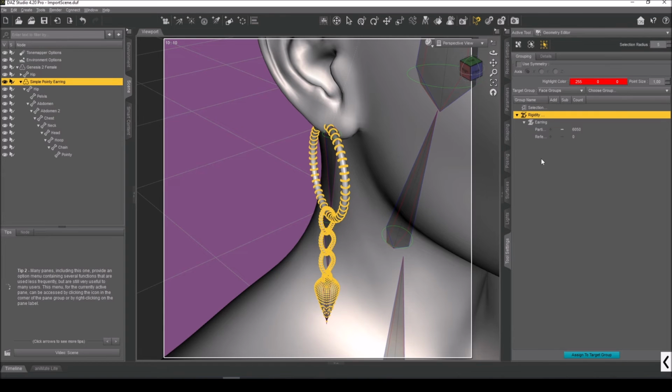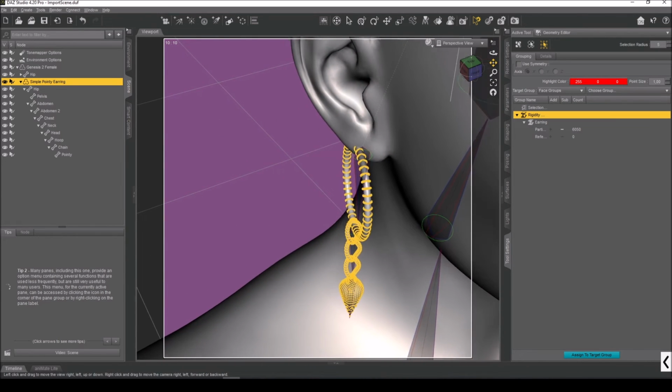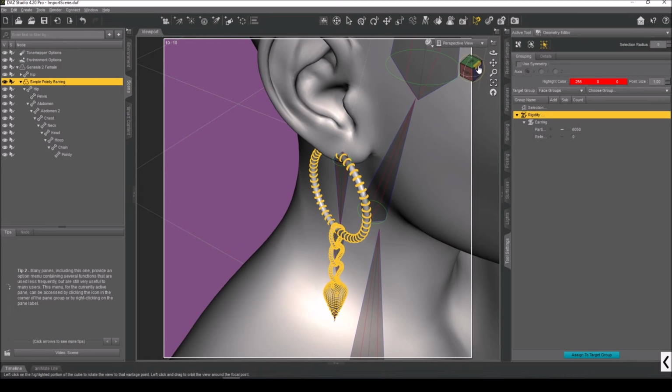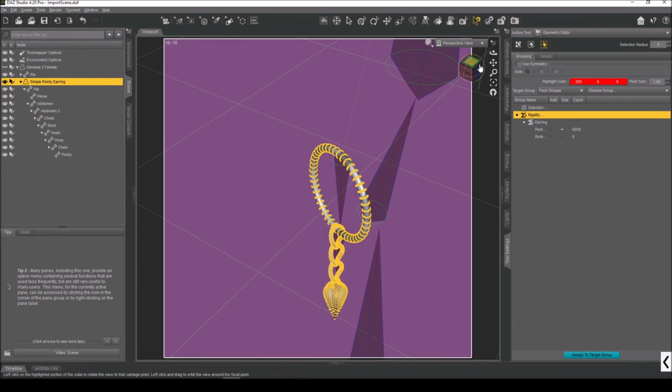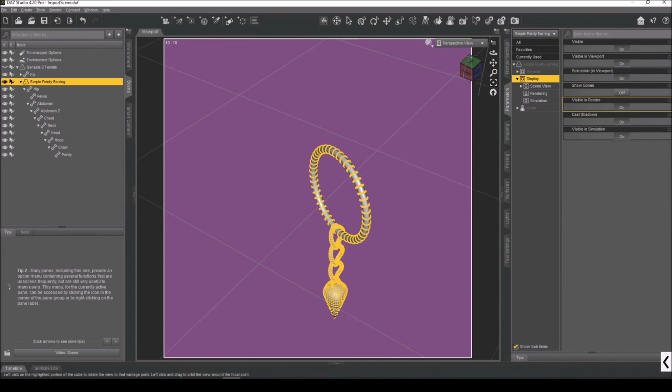And what we just did is we said, hey, for this object, everything that is currently marked, or everything of this mesh between all the points that we just marked, we want all of this to be of one rigidity group. The only problem is it doesn't know how it is going to deform it if there is a deformation, if a morph is happening. What am I going to do with this? And this is what we are going to do next. Actually, let me turn off the bones for this one.